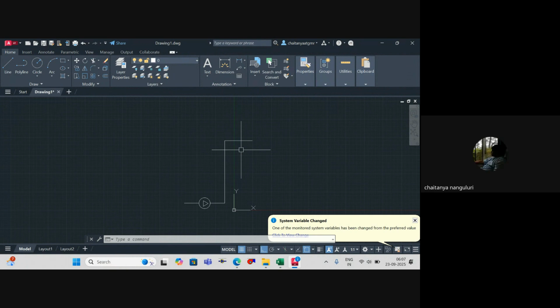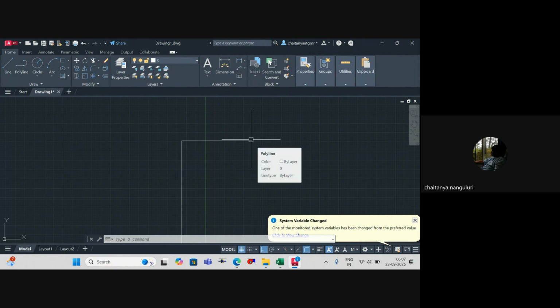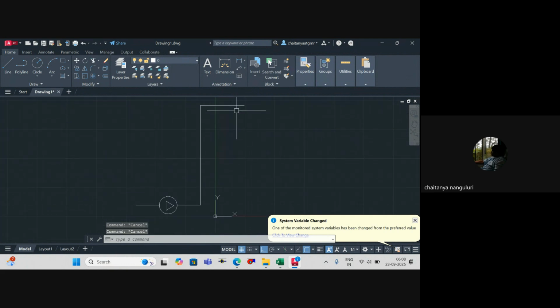For that case, when you consider your pump head, at the tap, if you just have atmospheric pressure, will it be sufficient? No. You should have certain pressure, like 1 kg or 0.5 kg. So at the terminal, whatever pressure is required, you simply call it pressure head.